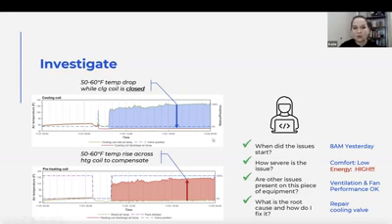Most likely it's the chilled water coil, but if I really want to know the severity of it, I'm going to look at what my heating coil is doing too. And I see that my preheating coil, which also controls to my discharge air temp, I have good programmers on my campus. They know what they're doing. They would never let a heating coil and a cooling coil operate at the same time.